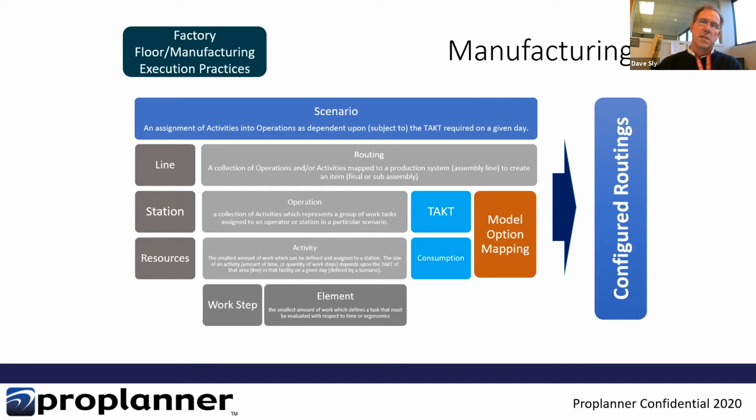Now that work represents a bunch of what we'll call high-level assignable tasks. When I say an assignable task, that means a task that could be put into one operation or another operation. It could be moved to a different operator or to a different station. So it wouldn't be like a grasp or a reach or a walk. That would be a time element. But a task is actually put a bolt on, put on a bracket. We're assuming that those would be things that could be assigned to different people and done in different stations.